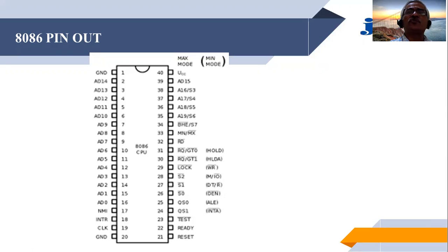So those lines which have multiple functions are required to be demultiplexed in the external world, so that we have the address lines and the data lines separately, not multiplexed, external to the system. When we talk about the memory in the real world, which is always external to the 8086, it is in this world that you have the memory devices which can be interfaced to the 8086.